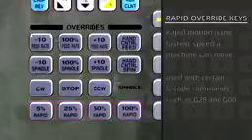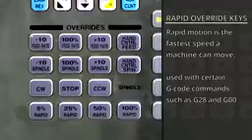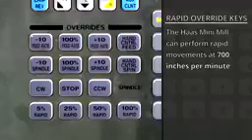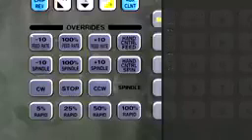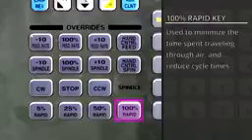Rapid motion is the fastest speed a machine can move, and is used with certain G-code commands such as G28 and G00. The Haas mini mill can perform rapid movements at 700 inches per minute, while other machines can exceed 1,000 inches per minute. When running verified and proven programs in production, 100% rapid is used to minimize the time spent traveling through air and reduce cycle times.